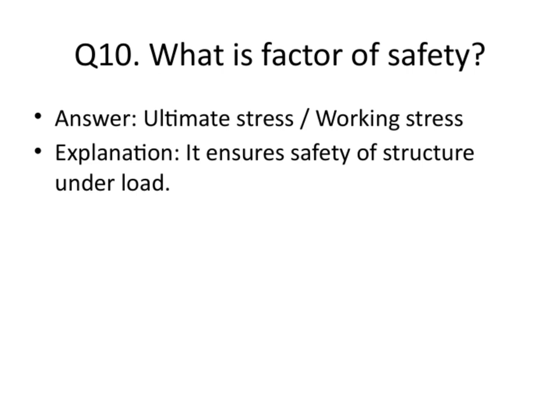Moving on to the next point, the question is, what is the factor of safety? This is a critical concept in structural design. The factor of safety is essentially a safety margin the engineer applies to account for uncertainties, like material imperfections, unexpected loads, or future deterioration. In simple terms, it's a number we multiply the actual or expected load by to make sure the structure remains safe, even if conditions are not exactly as predicted.